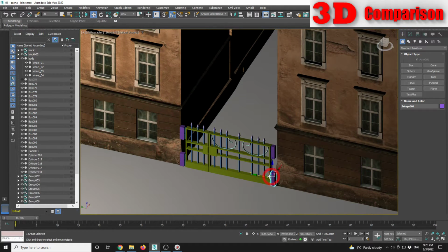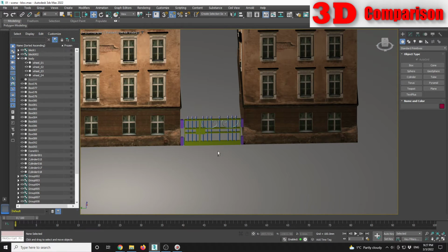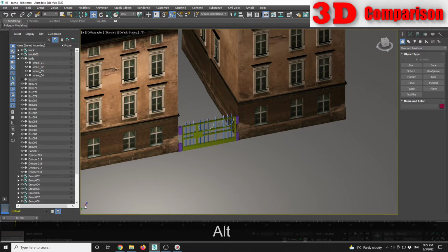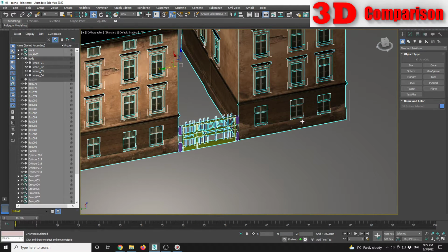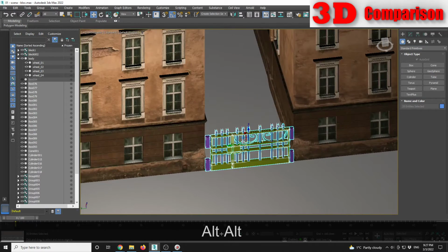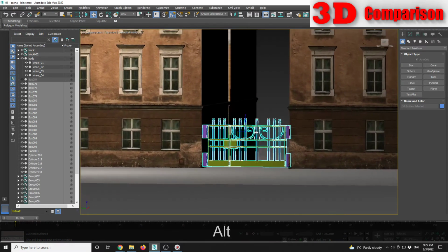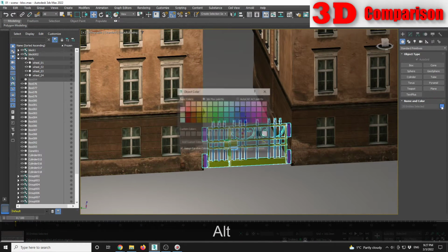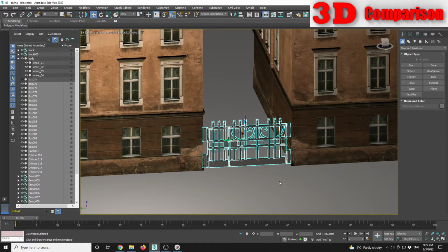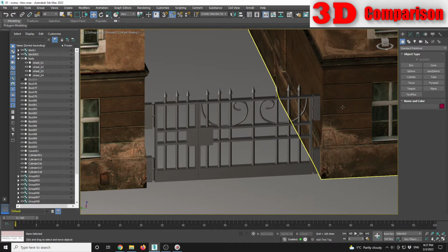Now we're gonna take a look at the door. I'm gonna have it all selected and translated on the x-axis. So like this, hold down Alt, deselect the two blocks, and have the gate positioned somewhere over here. I'm gonna also add maybe, let's say, a gray color for this gate, so it looks better in only one color. Now we're gonna do the grouping and define the animation.